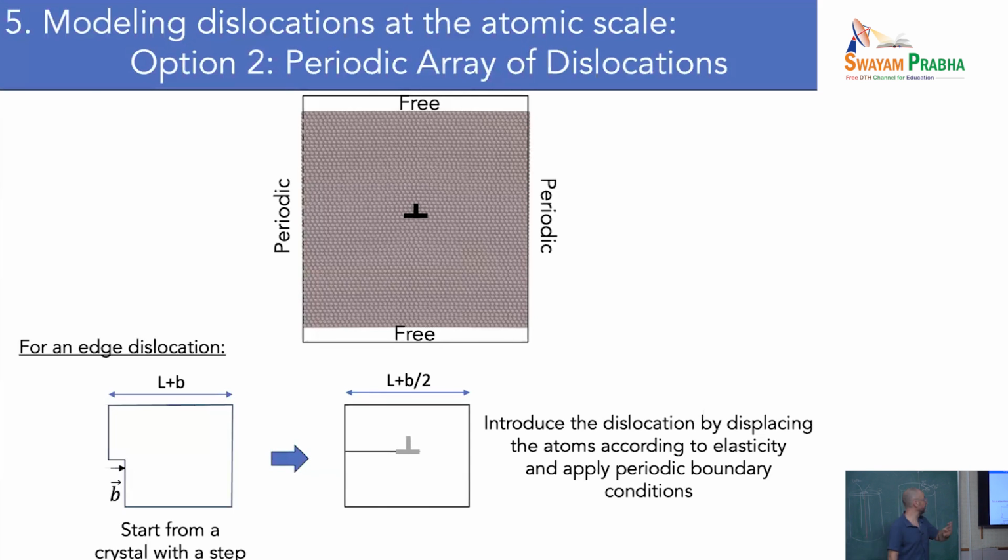You don't need to. So if you do that and you just let it free, the dislocation, if it's an edge dislocation, can only move along that plane. So it's going to stay where it is. It's not going to go to the free surfaces. Not about that dislocation, but about the atoms and the surface. If it's a free surface, the atoms will see that there's a free surface. They will relax, but nothing else will happen.